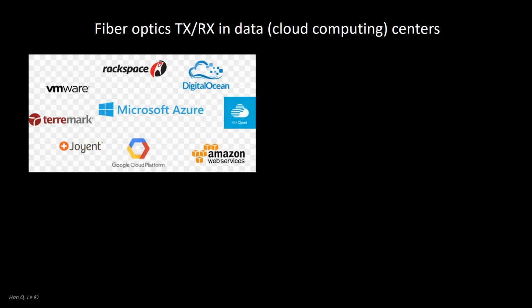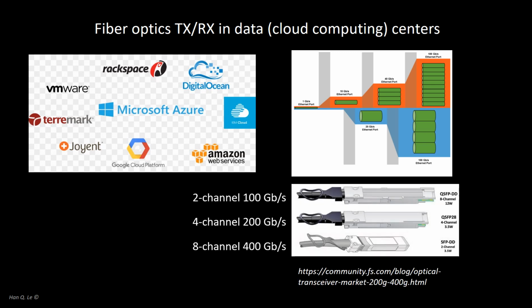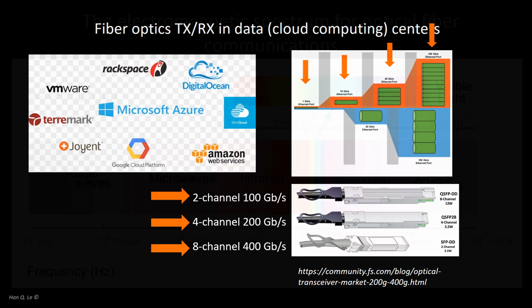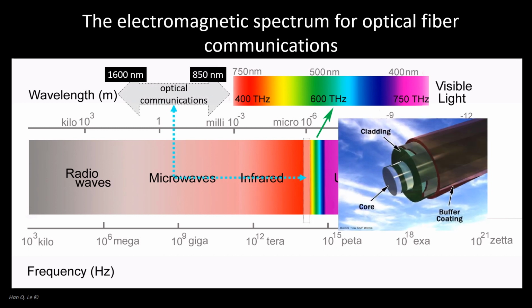As the computing power of a data center increases, so does the demand for data rates. 1 gigabit Ethernet was once considered ultra-fast, then 10 gigabits, and now it is several hundred gigabits and increasing. Another requirement besides the frequency is that the electromagnetic waves must be transmissible with little loss in the conducting media. Hence, for hundreds of gigabits per second, light waves of the frequency range of several hundred terahertz in low-loss optical fibers are presently the best technological solution to this demand.